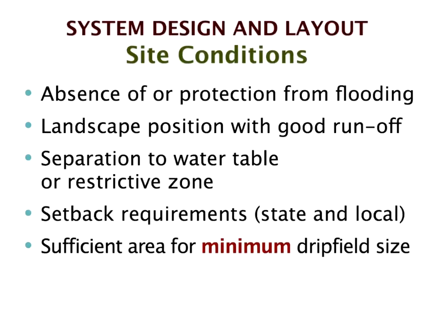System design and layout. You want to know about the absence or protection from flooding. Sometimes the designer has to include drainage ditches around a drain field in order to achieve protection from flooding. Landscape position with a good runoff. You don't want the rain to be soaking into the drain field.